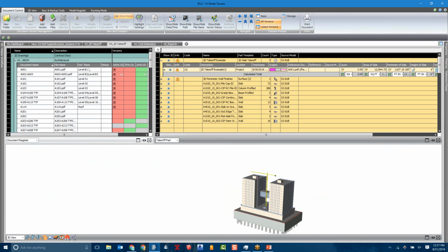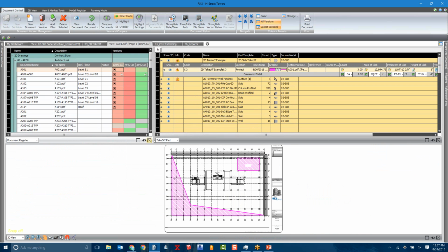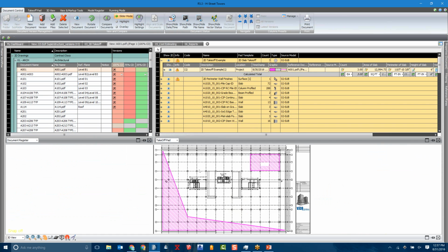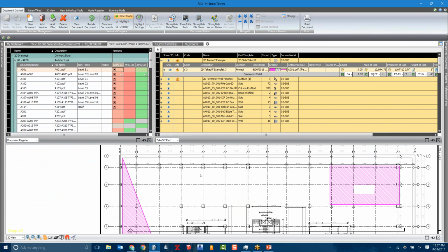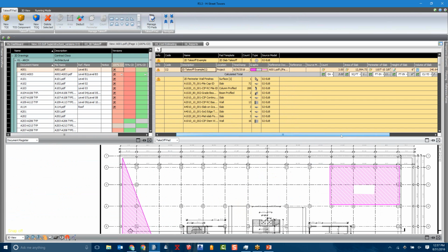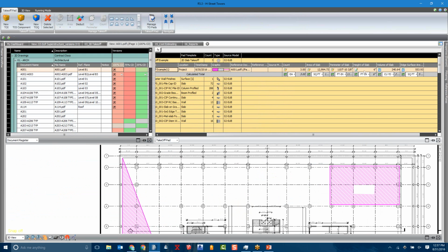So I have my 2D documents. Again, we have our register here and we have our drawings. Say I want to do a takeoff of, and I've got some takeoff here that I've already done, but let's say I wanted to take off another portion of this project. I've set up a takeoff item with various takeoff quantities. Some of the quantities that I've created are area of slab, perimeter of slab, height of slab, volume of slab, and edge surface area. So I want you to focus here in on these quantities. You can see I have 12,000, 1,100, I have 6 inches, 240, and 553.